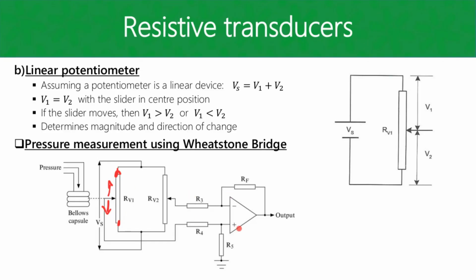A differential amplifier isolates your output from any grounds, and that can give you more reliable results than using just a straightforward inverting or non-inverting amplifier, measuring directly from your transducer.